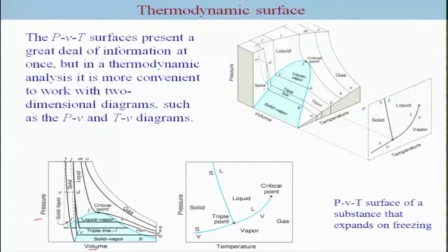This is the pressure and volume again, and this is a little busy plot. So, again this is a critical point, this is the two-phase region for the solid vapor, and this is a two-phase region for the liquid vapor, and this is basically the region where the solid and liquid coexist, and of course, this is your solid region, and some volume of course cannot be accessible. So, this is much easier in the PT diagram, and that's the reason that it is usually used in order to explain the phase transition for a pure substance.